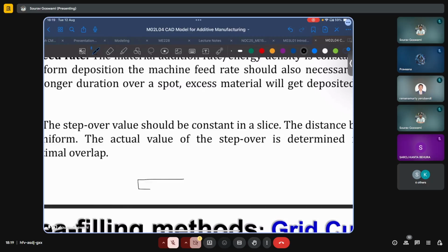Typically, when we plan our 3D printing process, say for the simple example of a cuboidal tower, this is our substrate. Typically, say a flat plate of a certain minimum thickness. For the machines we use here, it's typically specified as 1 inch or 25 mm. The idea being that it should be thick enough so that it does not warp easily. But what is warping? And say we just slice it using some uniform, planar slicing method.